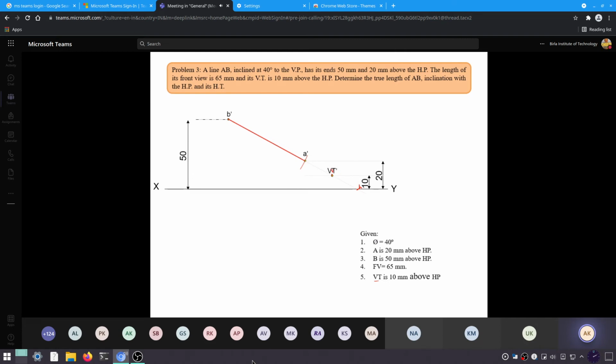So you'll see in the animation, capital V is VT, and this is small h. I'll just rub it so that you can see it in the animation. We've written h dash, but you can write h also, that is completely fine. If you draw a line perpendicular to XY from both the lines, VT and h dash, and drop it to XY, this will give you what?